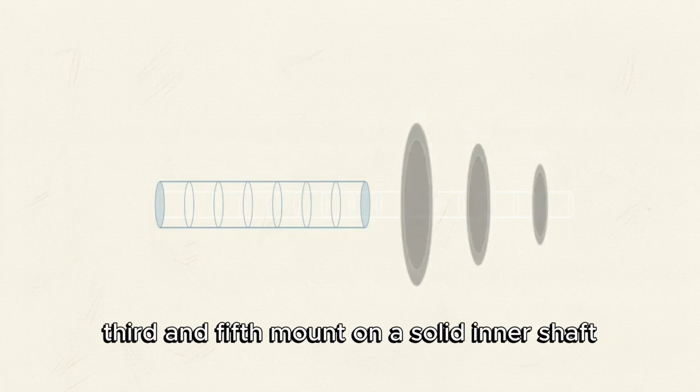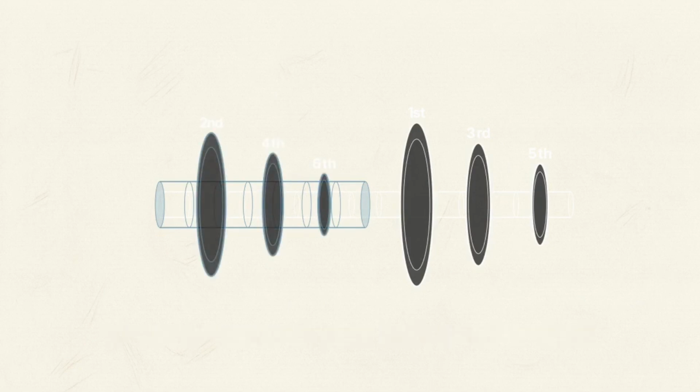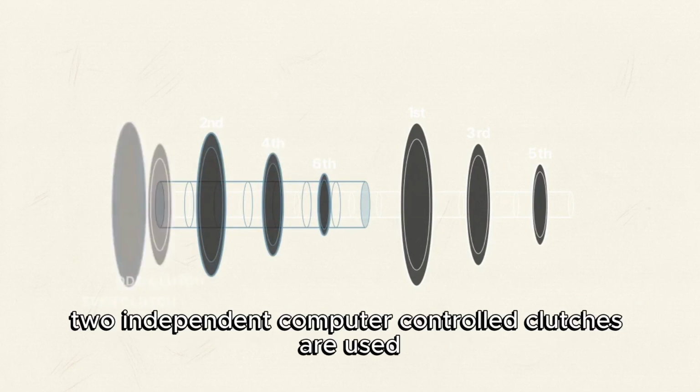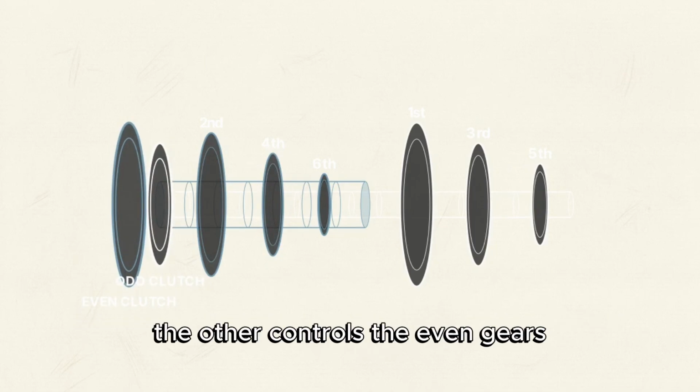A DCT nests two separate manual gearboxes. The odd gears, first, third, and fifth, mount on a solid inner shaft. The even gears sit on a hollow outer shaft. Two independent, computer-controlled clutches are used. One manages the odd gears, the other controls the even gears.